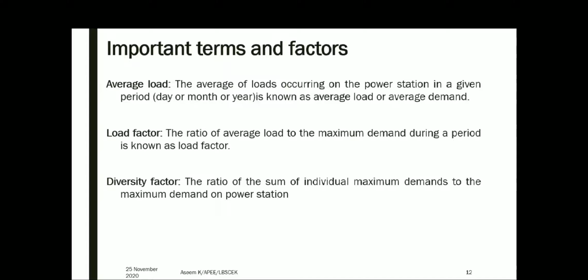period. The average load you can calculate as the area under the load curve divided by the total time period. And load factor is the ratio between the average load and the maximum demand during a period. Average load divided by maximum demand is the load factor.